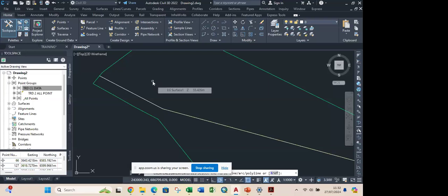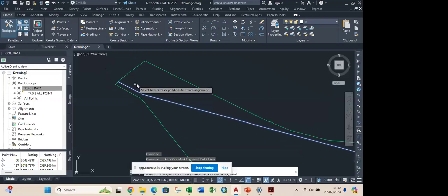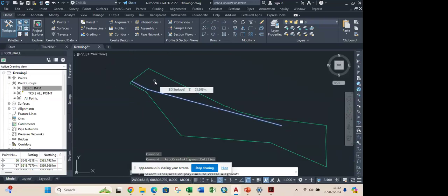So you see the essence of using a polyline. If it's single lines, you have to go and select each line individually, clicking on them one after the other. But if you select a polyline, you select the whole line from the start to the end. You can see it's highlighted everything from start to end. So it's always good to use a polyline when you're doing your road design. You can draw the line first, then trace with a polyline across the line. Or if possible, you can use the PEdit command and convert the line to a polyline in AutoCAD.